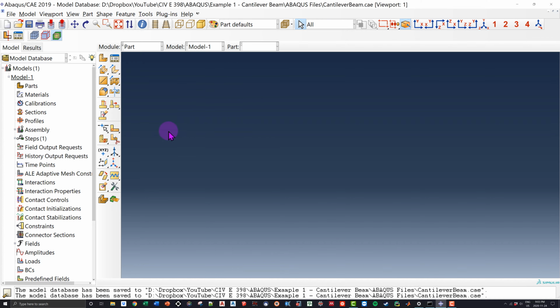All right, so that's going to be the hardest part. A lot of people run an analysis and go, Clayton, where the hell is my actual analysis file? It just disappeared on me. Well, it's probably in your temporary folder, because you need to define both where you're going to save the model as well as where you want to send the outputs of the model. All right, so that's the first little tidbit. I'm not going to go over that in every model because once you know it once, you're going to know it forever.